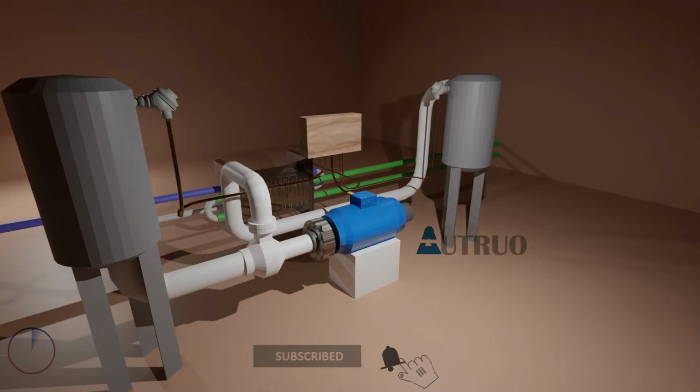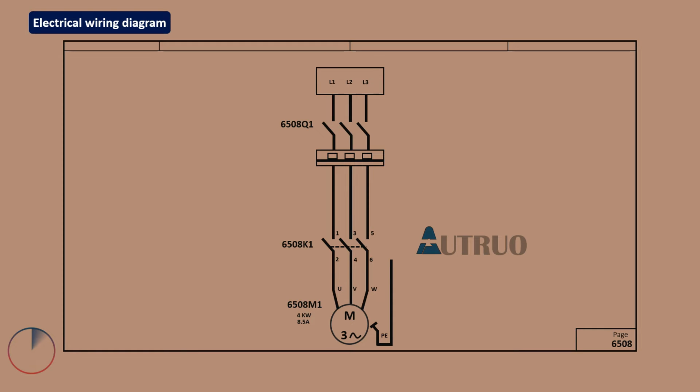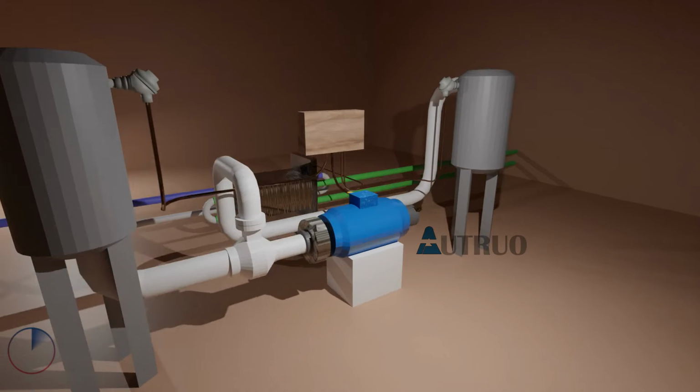After the cable has been terminated to the appropriate terminal by the designer, the cable is tagged with alphanumeric inscriptions, also known as a tag identifier. This tag identifier is linked to an electrical document known as the electrical wiring diagram. The tag has a set of numbers and alphabets. This alphanumeric inscription will be used to locate the installation page in the electrical diagram. Let's look at a typical example.